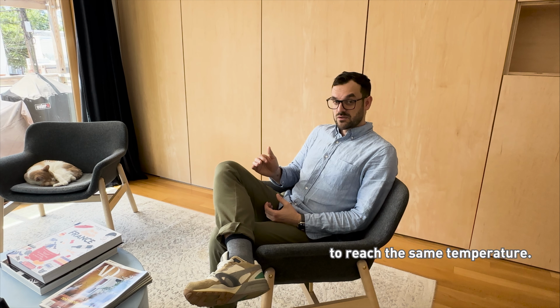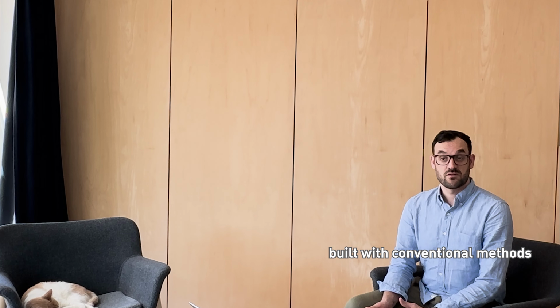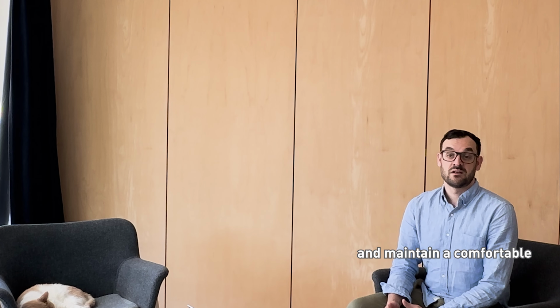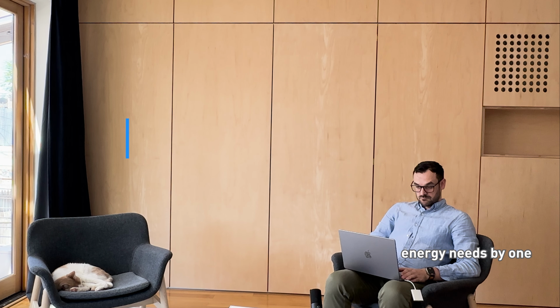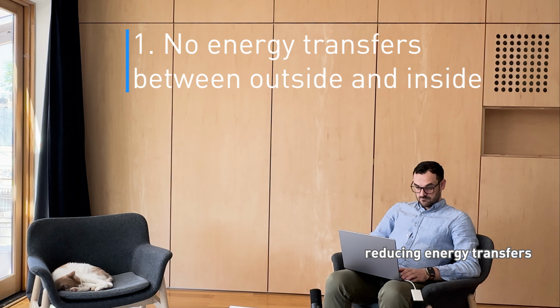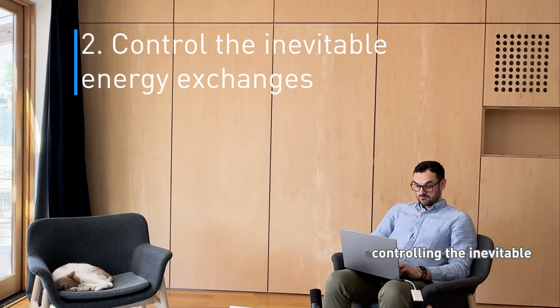When two objects with different temperatures touch each other, they always exchange energy to reach the same temperature. A building's interior and the exterior are no exception to this rule. As a result, homes built with conventional methods require a lot of energy to battle the energy exchange and maintain a comfortable indoor temperature. Passive house is intended to reduce these energy needs by 1. Reducing energy transfers between the indoor and the outdoor as much as possible, and 2. Controlling the inevitable energy exchanges.